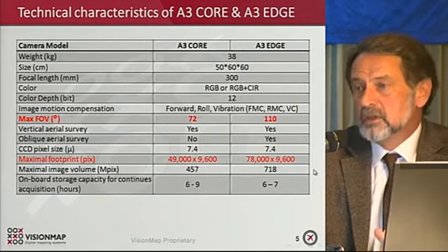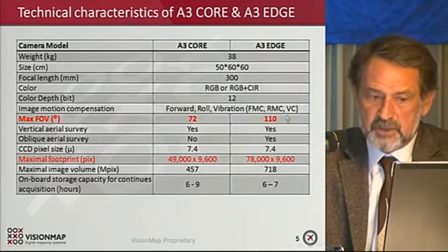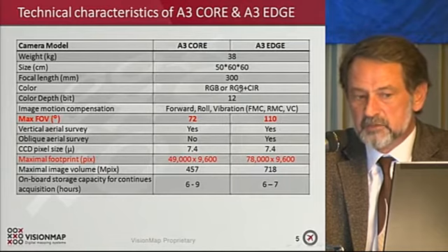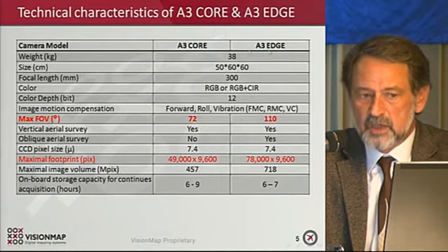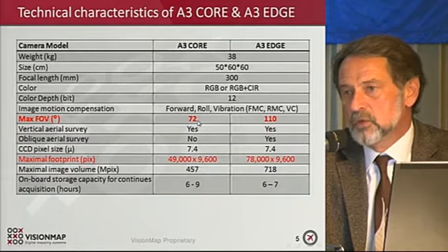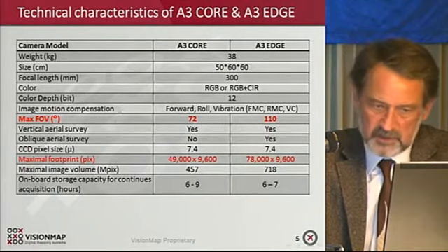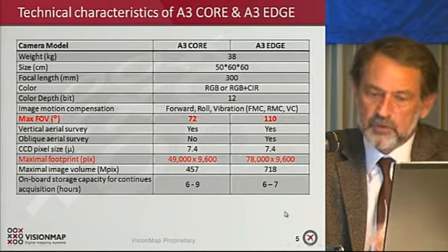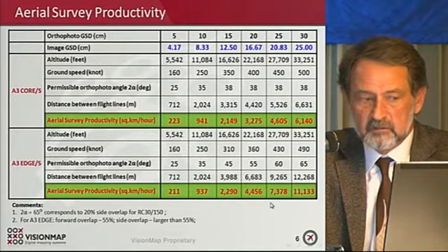That allows to fly high and see wide and far. You can have very good ground sampling distance. It delivers in RGB or RGB plus CIR. This is where the difference comes: 72, 110 degrees. Other parameters are more or less identical.